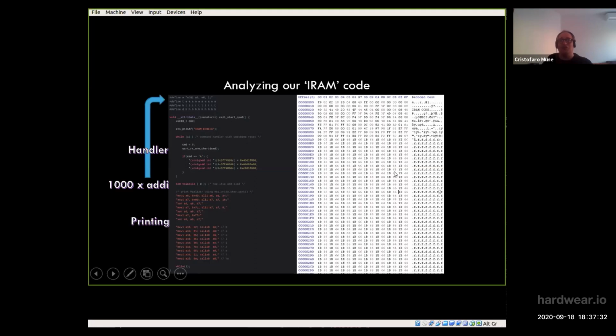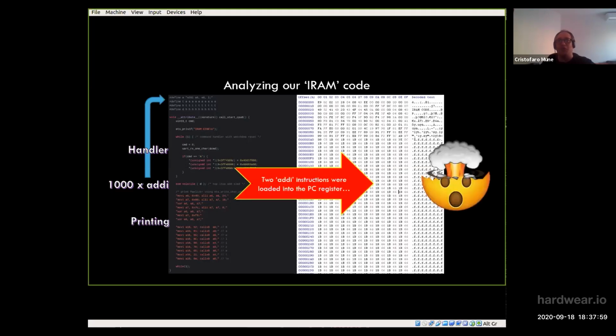So just to make you think about it. We put this into memory. The bootloader is overriding this. We glitch while the copying is happening, and out of magic, the value which was already there in SRAM, which was being overwritten, ends up in the program counter. If anybody has a good explanation for this, we would like to hear it and add to our hypothesis.